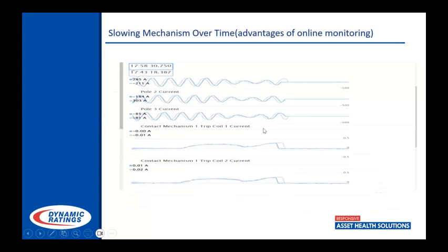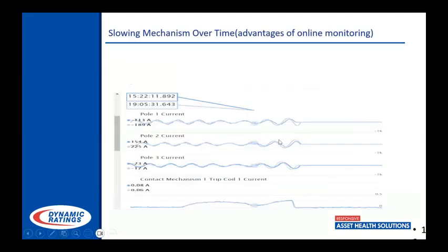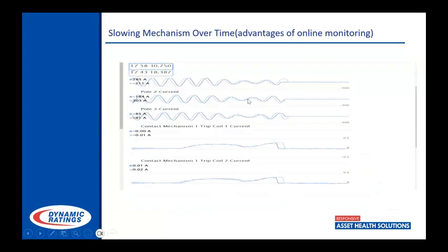However, at some point after that, they had an operation. And another good thing to make note of is this was actually at a renewable facility. So this breaker is getting operated once or twice a day, every day, switching between solar and steam generation. So after 8 or 9 months, we start seeing this kind of signature. And for time, I just grabbed a couple of grabs out of it, but we're looking at maybe 3-6 milliseconds here with this one.